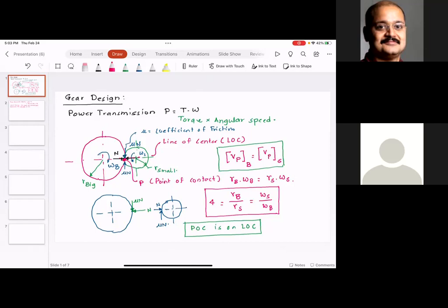If you look at the timing belt, it has teeth, which means it's like a positive power transmission device. At the same time, because of the compliance of the belt, it's forgiving to misalignments or maybe minute stretches, and there is a hysteresis also.